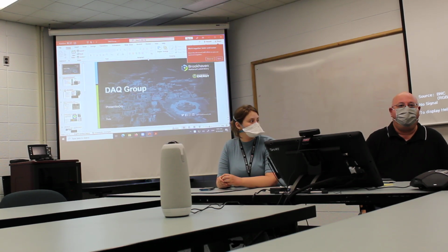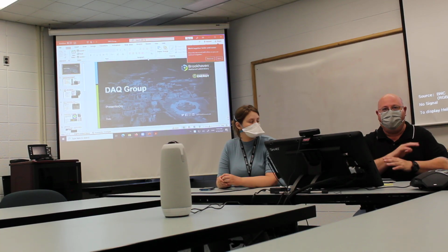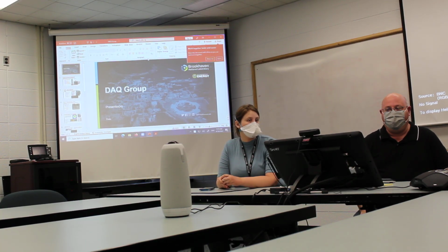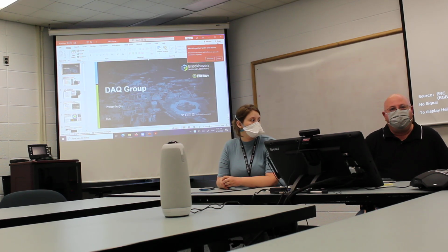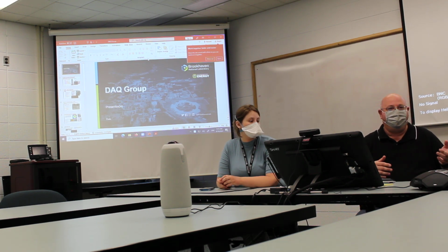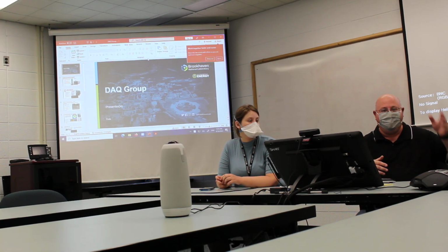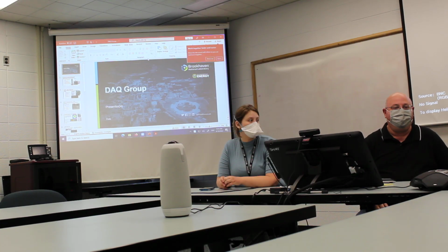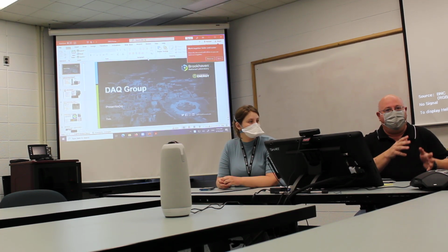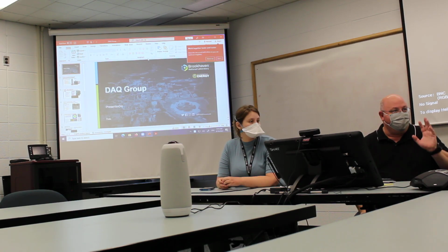To do real-time analysis, part of the problem is if you sample everything coming out of a detector, it's just going to be huge amounts of valuable data, and you can't do that. We have to come up with a way of triggering, knowing what data we want to collect. So in the past, we have an analog front end that looks at a signal and goes over a certain threshold, samples the data, calculates the timing. It's really easy using analog circuitry to do a peak finder and get accurate timing, sample that, digitize those 2 pieces of data, and send that over the system.